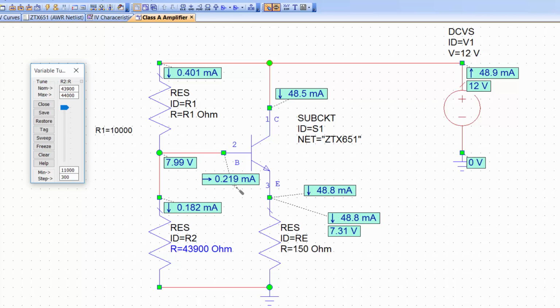We go back to having about 0.2 milliamps into the base of the transistor, and hence at the collector we re-establish a higher current. All the same, it is advisable not to have too high a value for R1 and R2. So try to choose a reasonable compromise and make sure that your bias conditions are met.